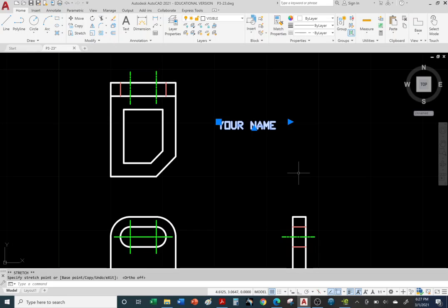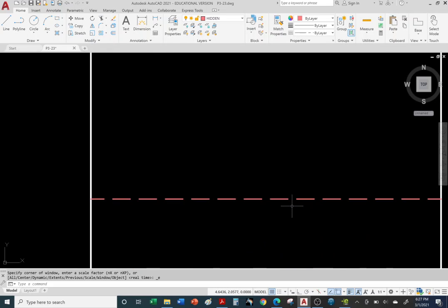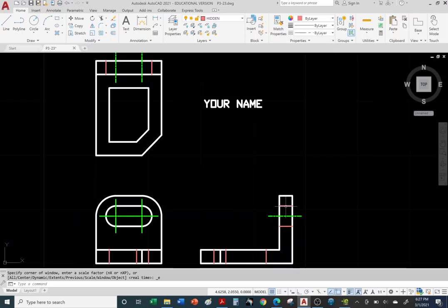Okay, so now some of you are like, wait, teacher, let me double click on the wheel. I cannot see the gaps, right? I cannot see the gaps, all right? So some of you probably remember, how do we change the spacing on the gaps? And it's LTS. Not as easy as 1, 2, 3. LTS. Don't you mess with me. And enter, right? There it is. Right now it's at 0.1. Let's try 0.01.